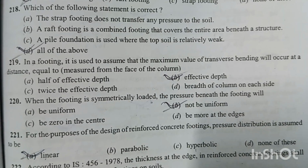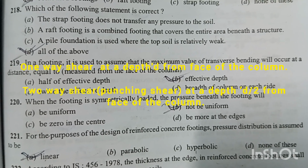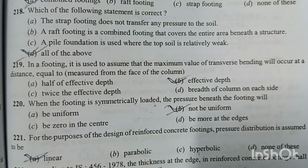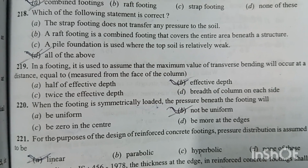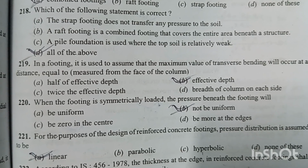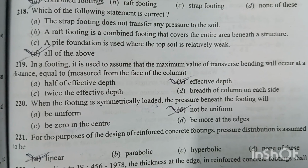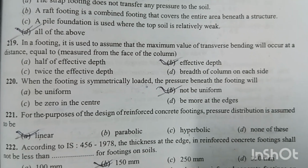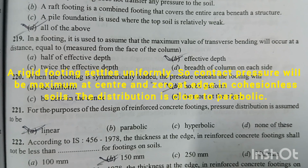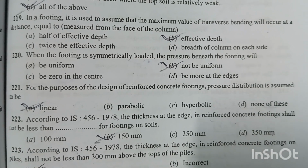Question number 219. In a footing, it is usual to assume that the maximum value of transverse bending will occur at a distance equal to effective depth, measured from face of the column. Option B is right answer. Question number 220. When the footing is symmetrically loaded, the pressure beneath the footing will not be uniform. Option B is right answer. Question number 221. For the purpose of design of reinforced concrete footings, the pressure distribution is assumed to be linear. Option B is right answer. Question number 222.